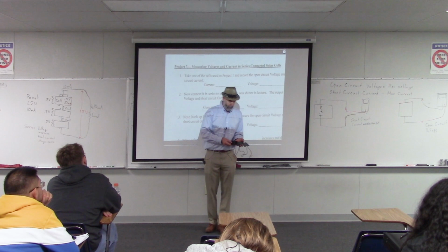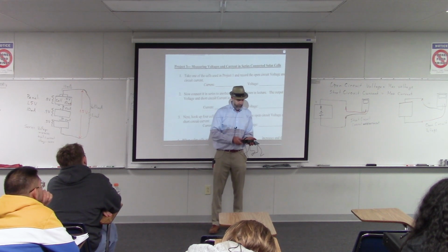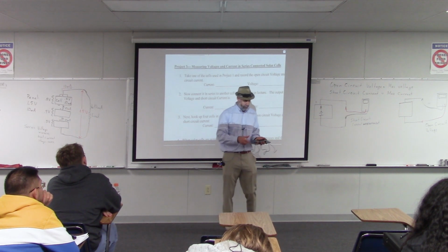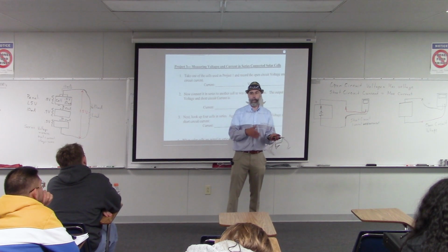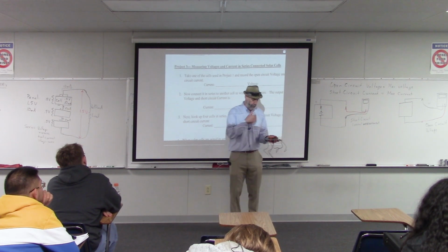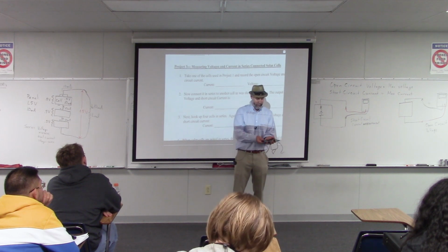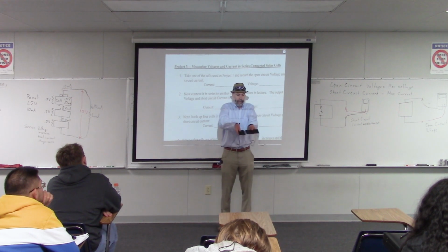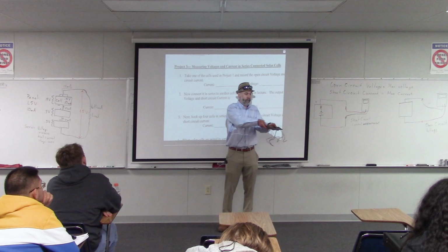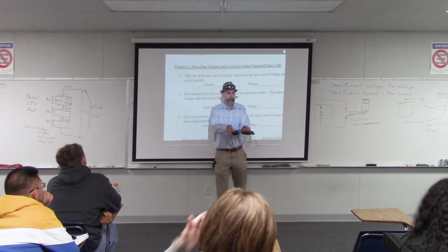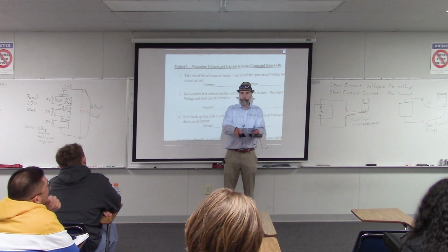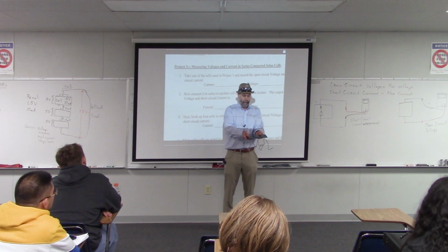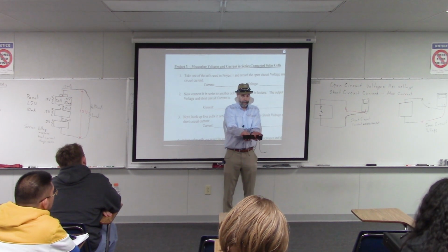Also, when you are holding these panels, it's important not to cover up any of the cells in the panel, because the electricity is flowing through each of these cells, and if you cover up one of them, you're blocking that cell, and so you're essentially blocking the electricity for the entire circuit. It's tempting to hold these cells kind of like this, but when you do that, you're putting your thumb over some of the cells in your panel, and that can be blocking the electricity. So if you are getting weird readings and you're not seeing any electricity, check your hand position. Make sure that you're not blocking any of the cells, okay?